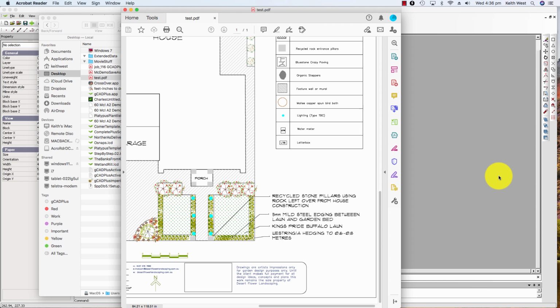I've moved to the bottom of the PDF file that's been generated by Save as PDF, and you'll notice on the left hand side here there is a scale bar. So it's very important to distinguish between Save as PDF. You'll get a preview which you won't be happy with, but if you install Acrobat Reader, you can open it up using the reader and in this case get a nice crisp result.